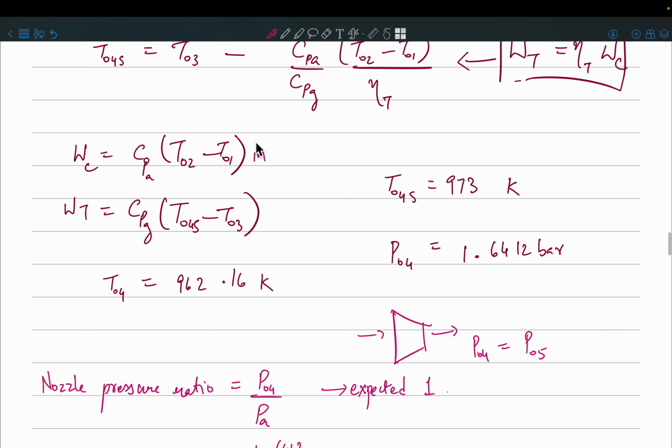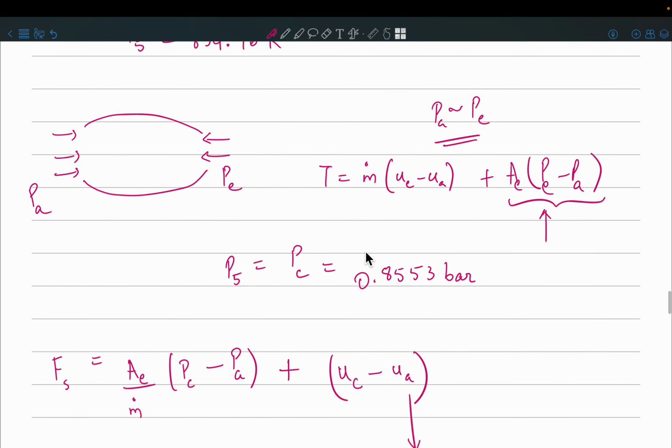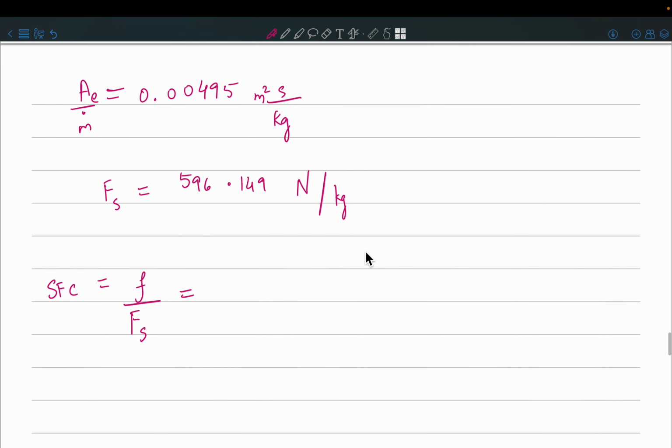There should be an m dot air term, and here there should be m dot air plus m dot fuel term, right? Now because you were just taking a ratio, and m dot f was very, very small, you neglected it, but ideally you should account for that in the calculation. Okay, and then by doing that work balance also you can get the fuel air ratio.